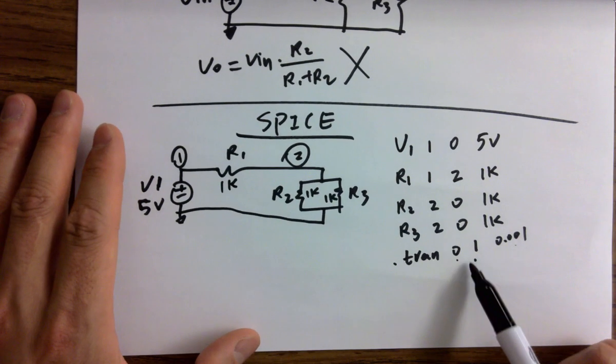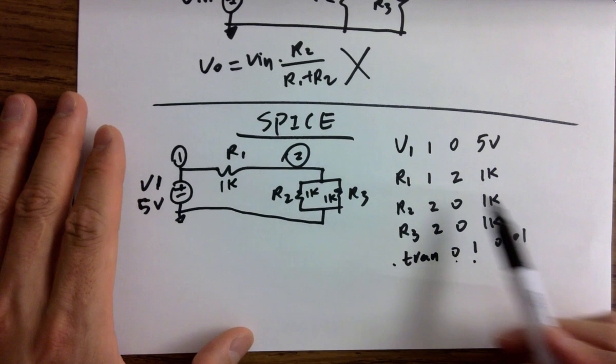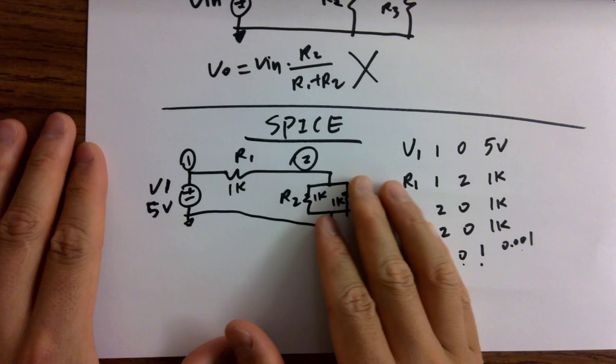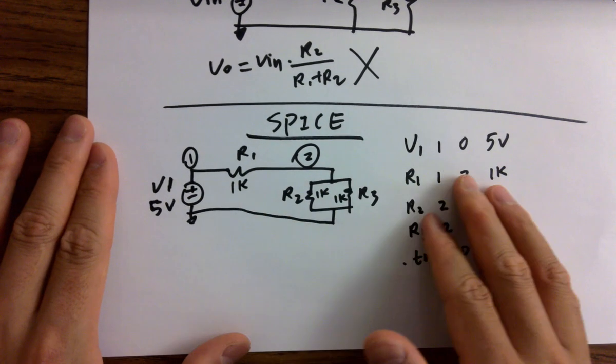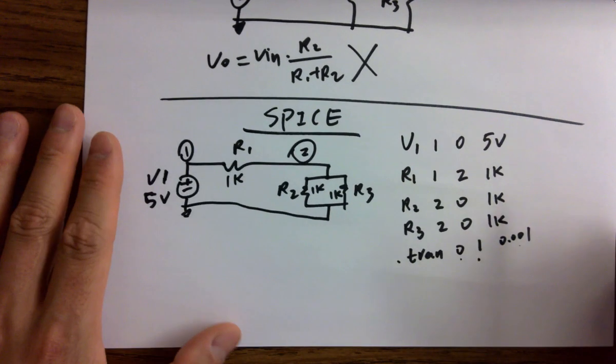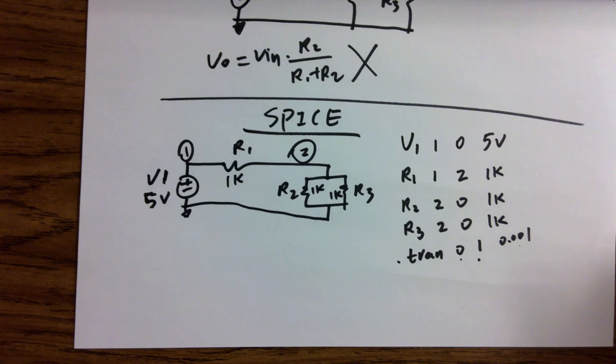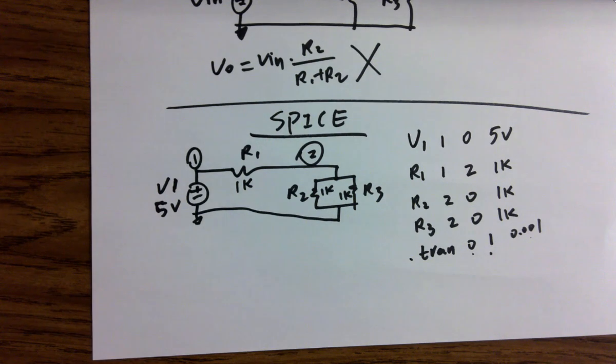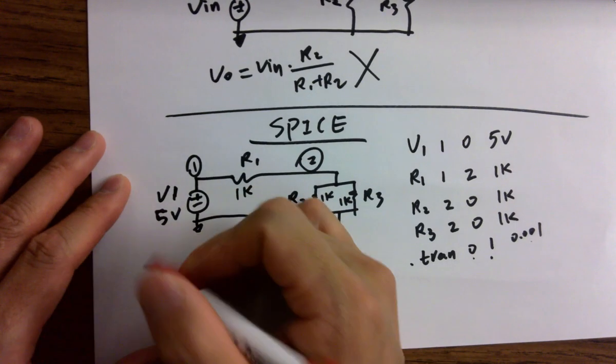So it's going to be a time domain for a 1 second analysis. It will be a straight line, because all these are static DC circuits. So a straight line will plot the voltage. You can plot the current. You can plot power. It's going to be just a straight line everywhere, right? Or you can do AC analysis. You can do DC analysis, and sometimes you can change the function, which is the one we are going to use a lot in our labs or in this class, which is called the pulse function.